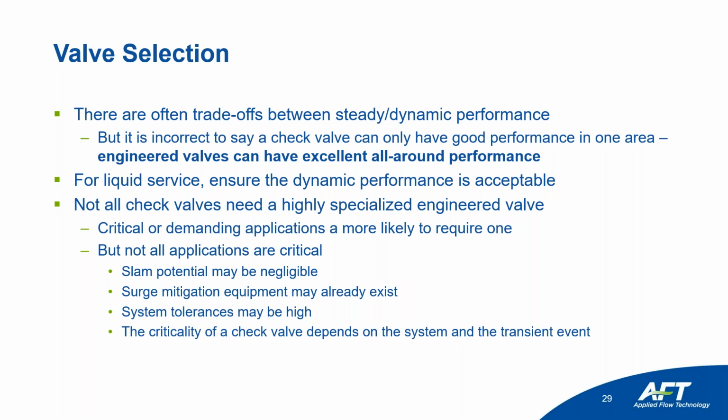dynamic performance, but it's incorrect to say that you have to choose one. Of course, we recognize this is often about capital expense. A valve that behaves well in steady state and has excellent dynamic performance is probably more expensive. And for that reason, maybe you don't always need it.